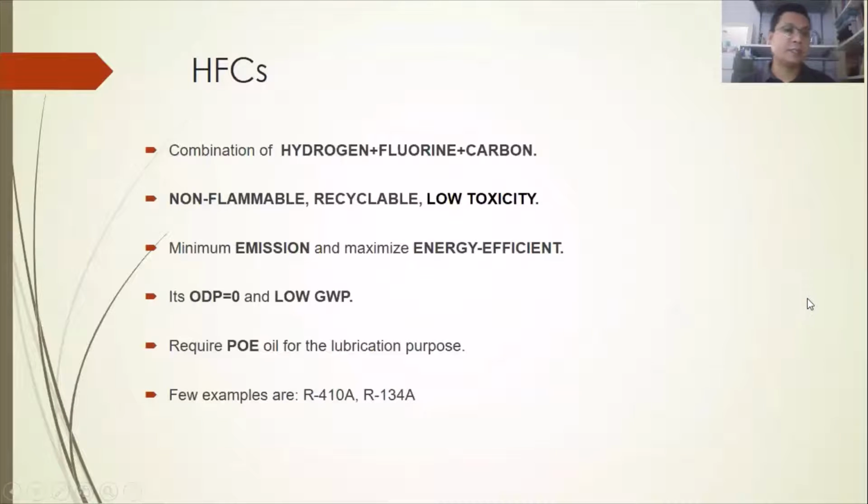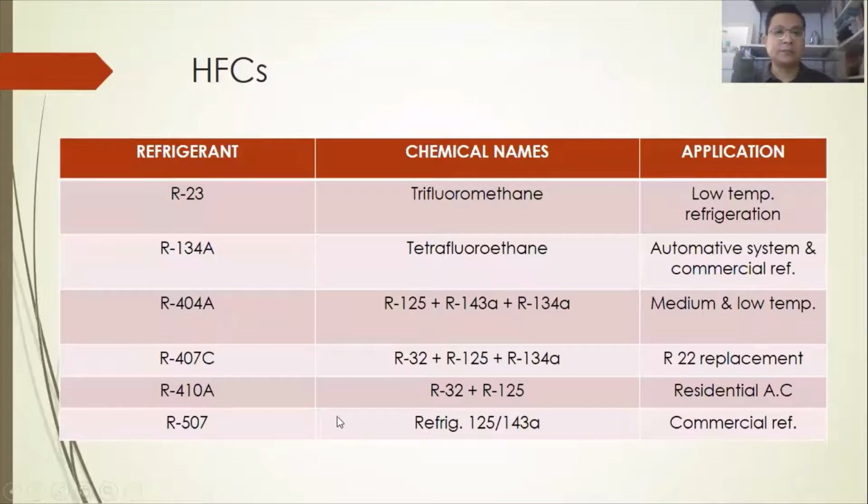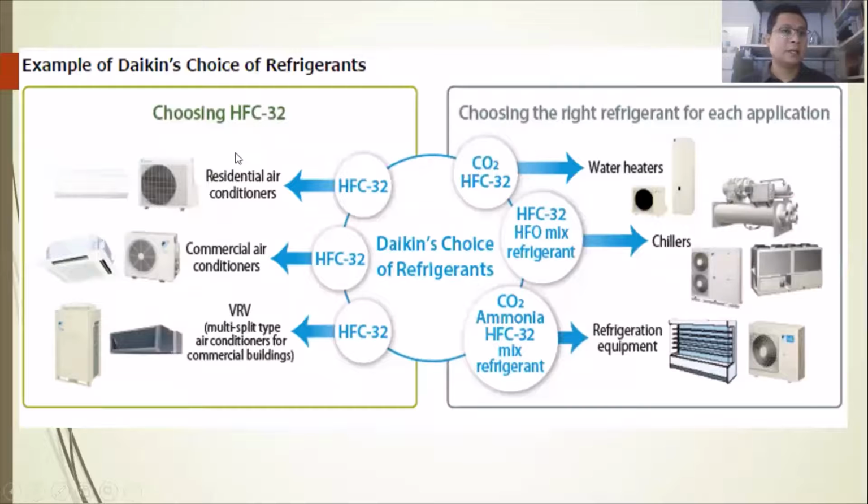Okay, in the group of HFCs: hydrogen, fluorine, carbon, non-flammable, recyclable, low toxicity, minimal emission, ODP also zero, low GWP, and requires POE oil for lubrication purposes. For example, R410A. Okay, this one is in the HFC group.